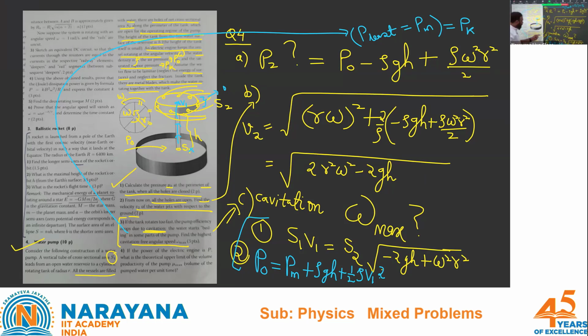That limiting omega or the omega max is the value where the pressure on the axis of the upper constriction becomes Pk. Because that is the least, and the saturation vapor pressure will first be reached there, cavitation will start from that point. So if I can avoid cavitation there, it will not be present anywhere else. So you just write and solve this equation.